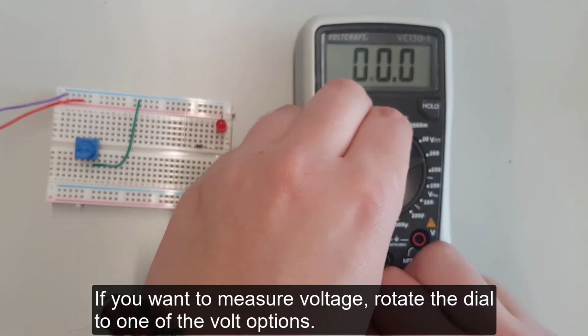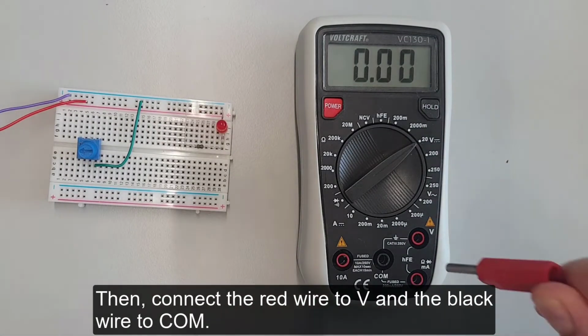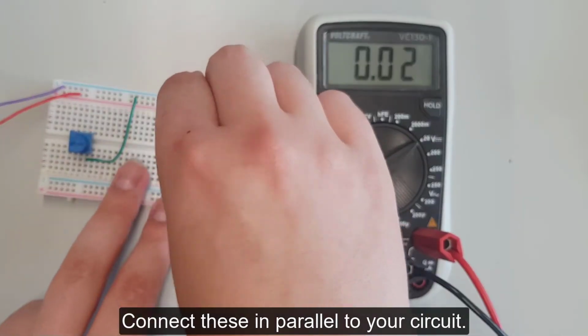If you want to measure voltage, rotate the dial to one of the volt options. Then connect the red wire to V and the black wire to COM. Connect these in parallel to your circuit.